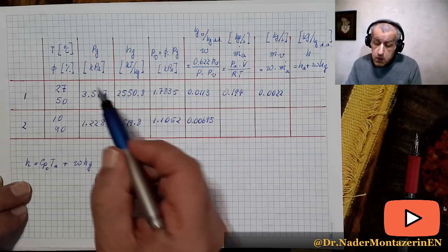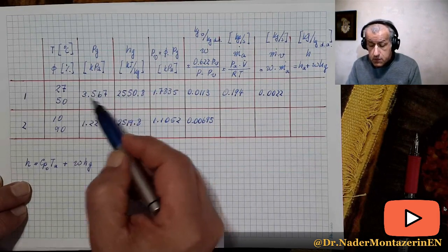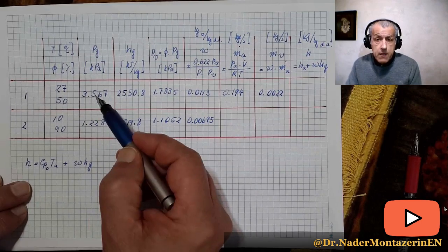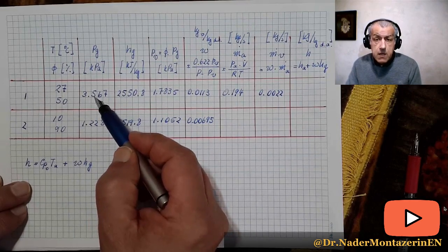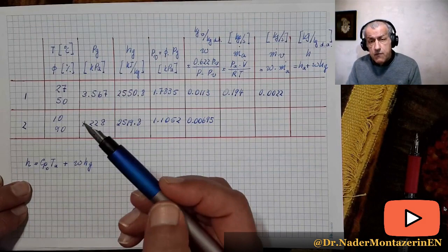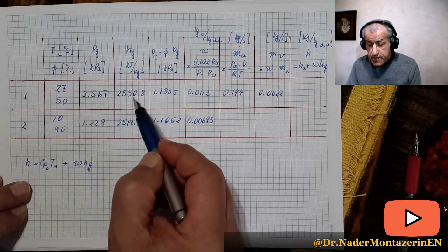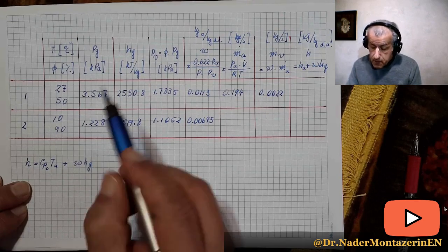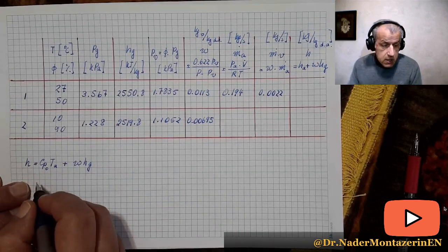We had the temperature, we were reading the saturation pressure, and therefore we just read the saturation enthalpy for the water vapor, and we can use it here.